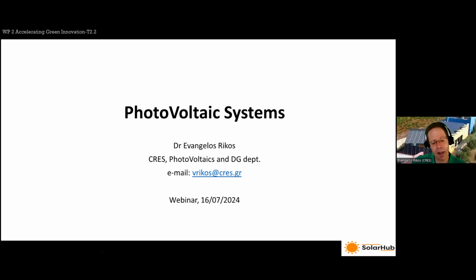Yeah. Well, the obvious answer, even though I'm still learning how to do that, to be honest, is that you don't consider a projection of full shading underneath the semi-transparent modules, but you need the percentage of transparency, perhaps, or an amount of radiation that still makes it to the ground, right? I guess that's how one should address the problem, because don't forget that we always have the diffuse radiation we mentioned way earlier in the presentation. It always exists and it will always be there.